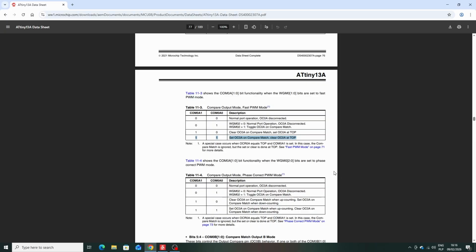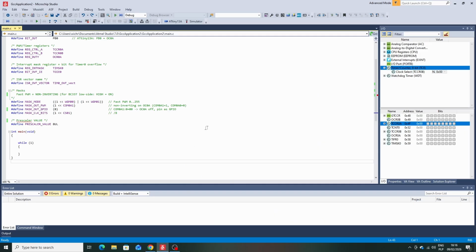In both modes everything works correctly, but the MCU pin state no longer directly represents the LED state. In one case high means the LED is on, and in the other case high means the LED is off.